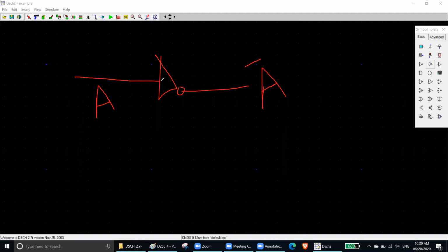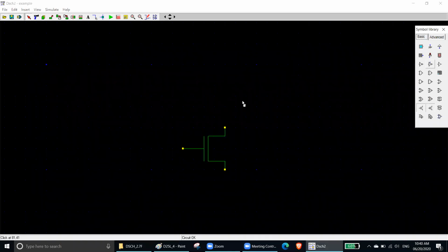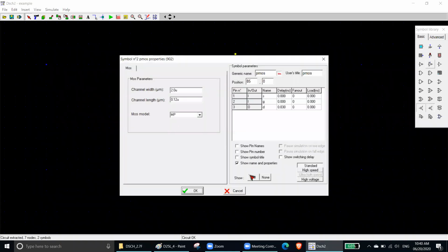We all know it, but we do not know how this NOT gate is made. Okay, with what your NOT gate is made of. We do not know it, so we'll design it first. Okay, let's see. Now your NOT gate design needs one NMOS first, then you need a PMOS, an NMOS and a PMOS.